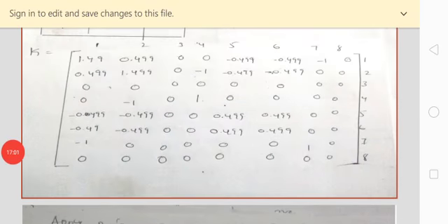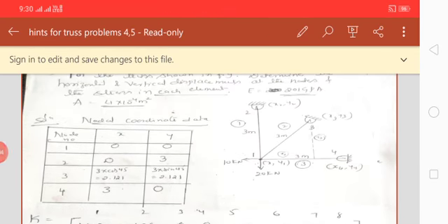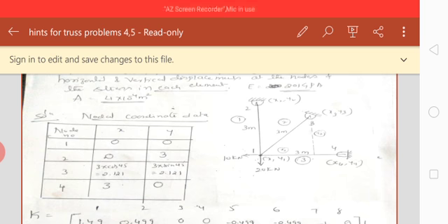Now apply boundary conditions. Just observe the figure here. It is easy for you because everything is completely constrained here. At node 1, there is no fixed support. While creating the model, at node 1 you have q1, q2. These are the two nodal displacement values at node 1 along x and y, and exactly at node 1 forces are acting. Loading conditions are acting, one along y and one along x direction. That means F1 and F2 are given. F1 is acting with a negative value, that is minus 10 kilonewton you have to take. For F2 you have to take again negative because it is acting in the downward direction, that is F2 is nothing but minus 20 kilonewton.